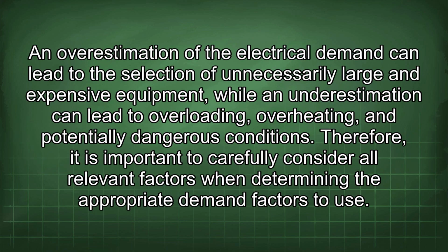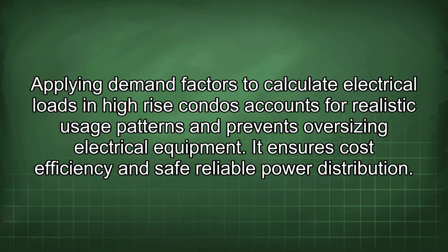An overestimation of the electrical demand can lead to the selection of unnecessarily large and expensive equipment, while an underestimation can lead to overloading, overheating, and potentially dangerous conditions. Therefore, it is important to carefully consider all relevant factors when determining the appropriate demand factors to use. Applying demand factors to calculate electrical loads in high-rise condos accounts for realistic usage patterns and prevents oversizing electrical equipment. It ensures cost efficiency and safe, reliable power distribution.